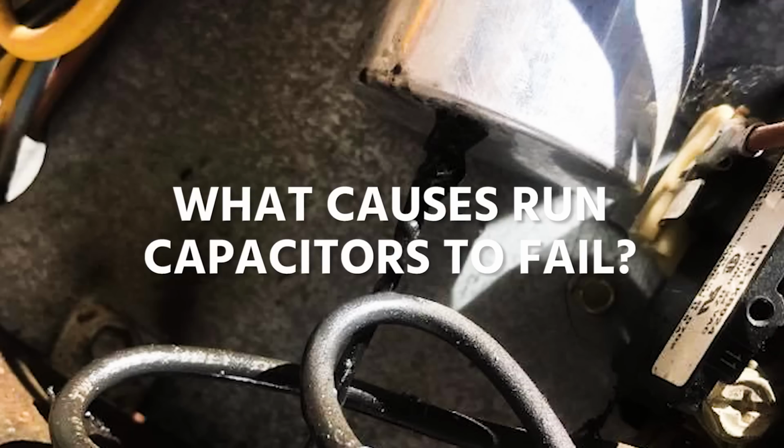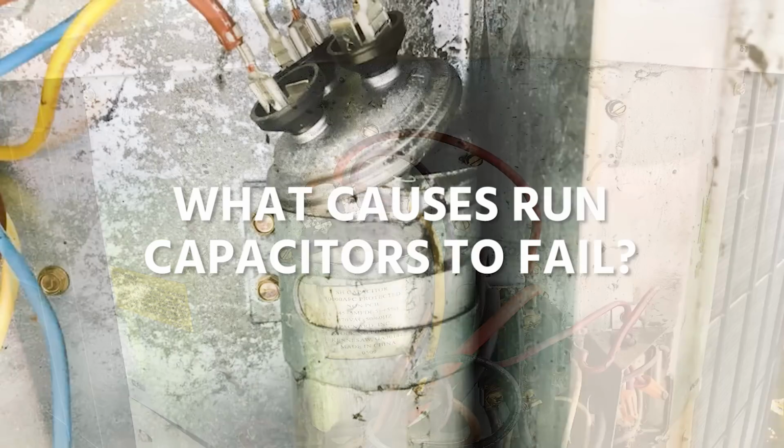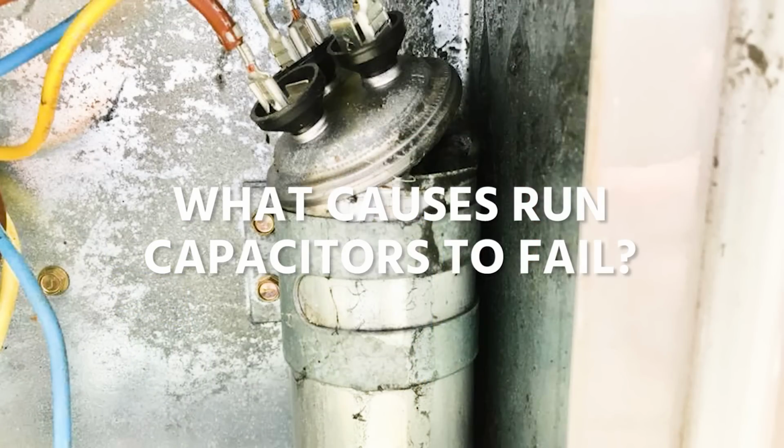Some of the common theories are that if your motor is drawing high amperage, that will cause the capacitor to fail sooner, so that something goes on inside the motor itself that causes the capacitor to fail. Many have said that they notice that a system that's low on charge seems to have weak capacitors, or a system with a dirty condenser coil seems to have more commonly failed capacitors. Some people, including my own brother, have said that they've noticed that capacitors seem to fail more often when the applied voltage coming in is low. And so I want to explore this.